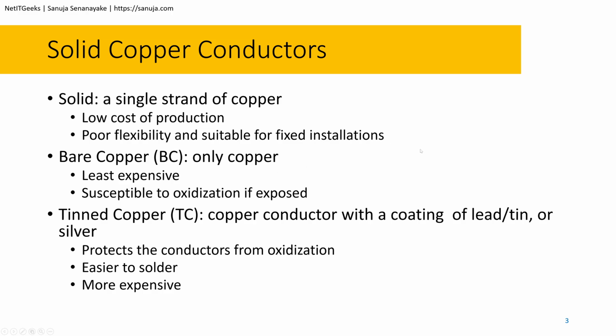What that means is that solid cables, because they have one thick copper conductor in there, are not very flexible. But because you don't need stranded wires woven together to build that core, it is much cheaper to produce compared to stranded cables.